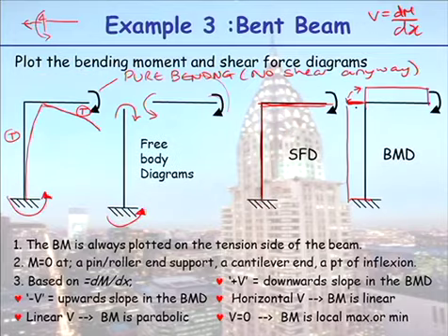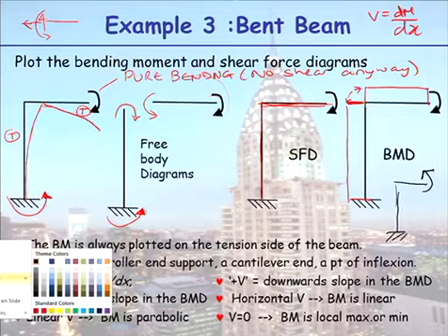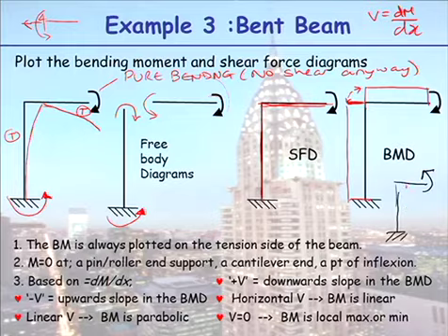So when you have an applied moment like so, your bending moments are both on the outside. If I have that same frame and I now apply a bending moment in the opposite direction, my bending moment diagram this time will be on the inside, and they'll overlap. But that value will be equal to that value. So your bending moments are either both on the inside or both on the outside, and they have the same absolute value.